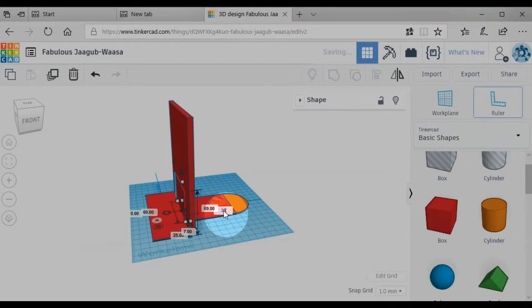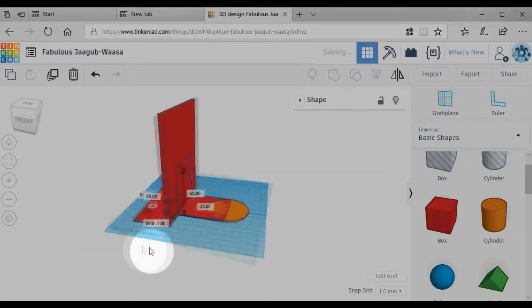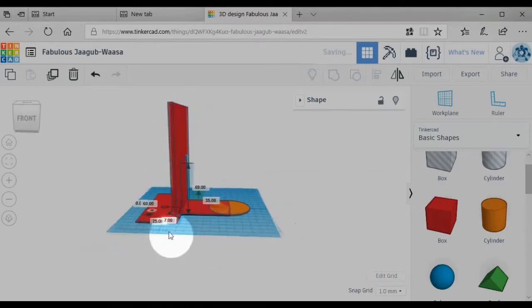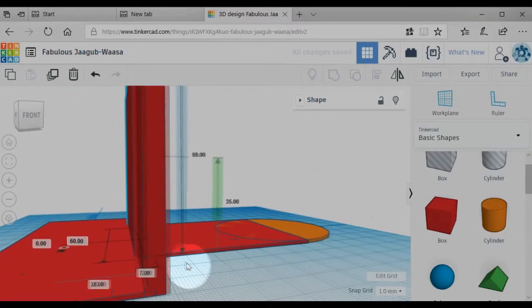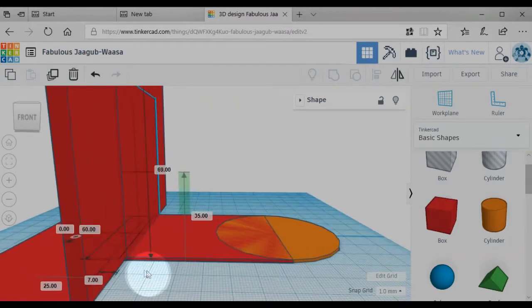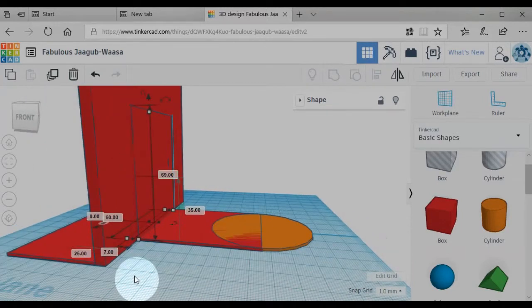It sits right on top of the base, so the base will be flat with no bumps or depressions caused by the hole. Notice that the box to subtract is slightly wider than the brace. This addresses a side effect of how the model prints. Any surface where the hole and the part touch becomes a film with 0 thickness. Logically, this may seem like a non-thing, but the printer will attempt to make it. The result is a thin, partially formed sheet that covers the hole and interferes with the print. The effect can be artistic in the right circumstance, but creates a problem when an actual hole is desired.